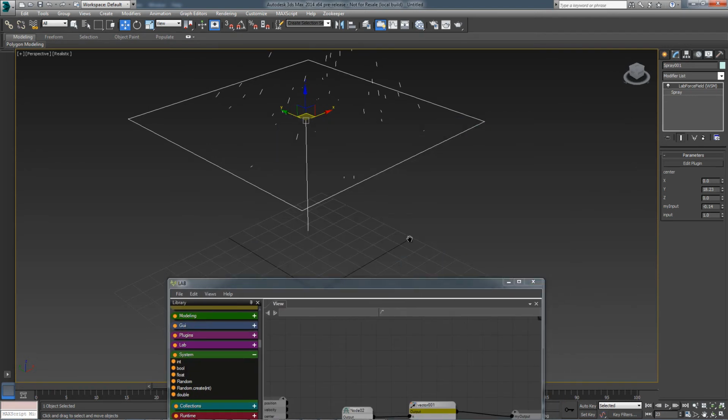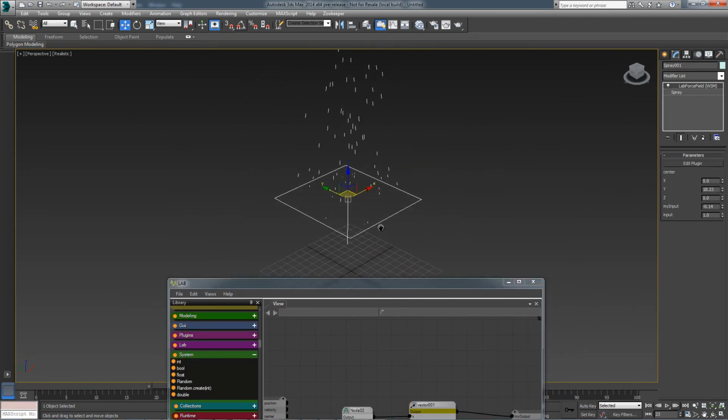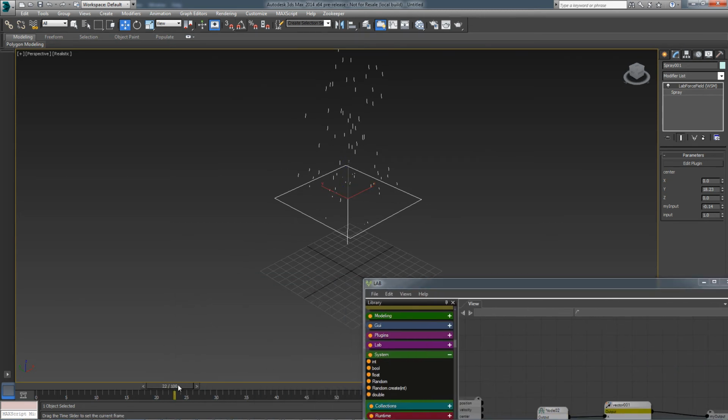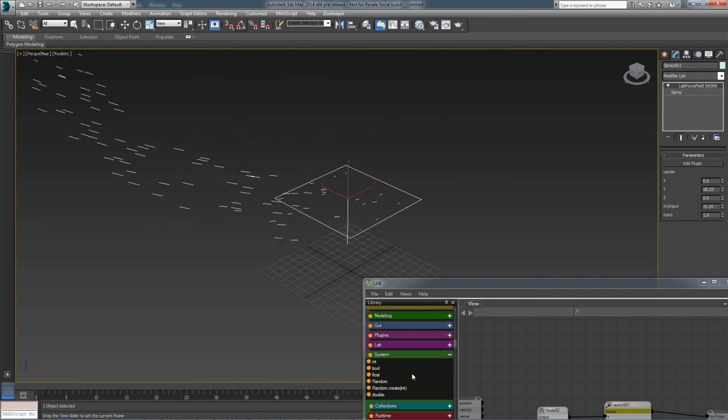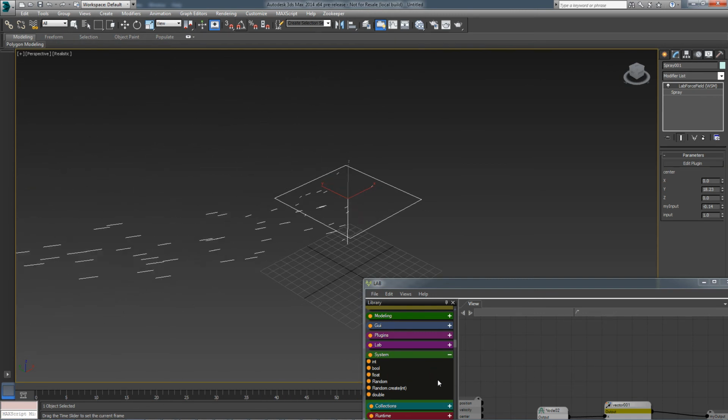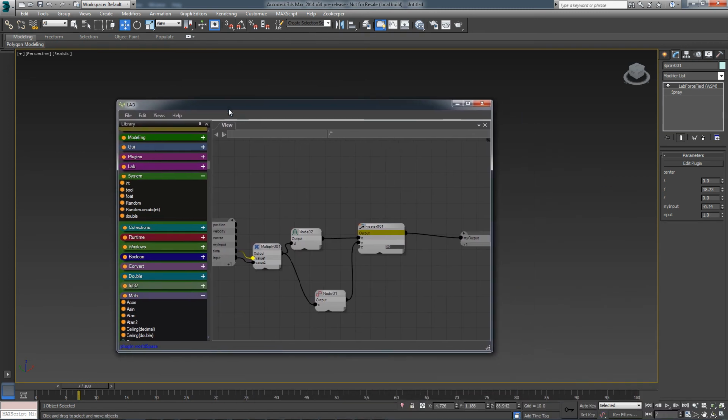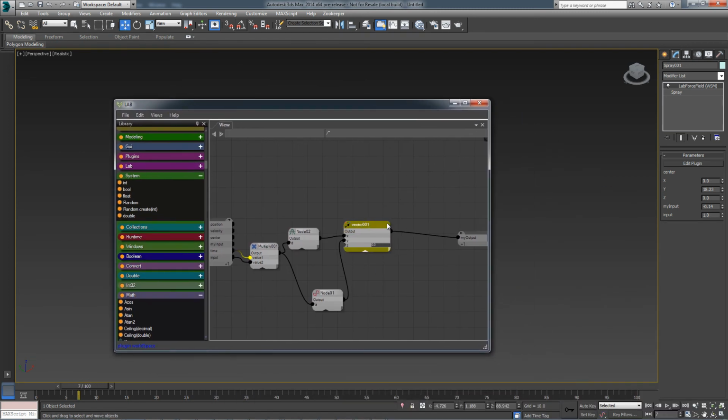And we can see right now that it did something, but it is really having a huge effect. So let me just scrub through the timeline, and it is already doing something interesting, but it is doing it way more than we want. And it is actually becoming more and more as the scene continues, so it is kind of just blowing our particles away. So to decrease this, I'm going to add another multiplier to my force vector.